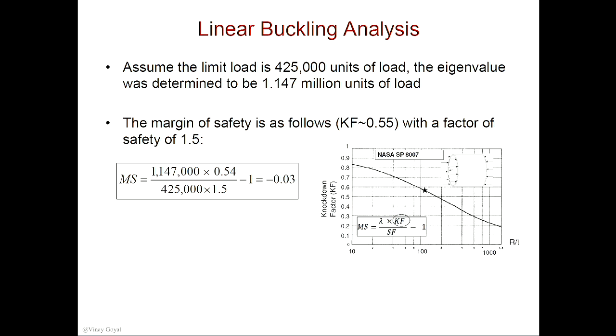And what I want to show you is how to approach the problem in a different way. Okay? What if I now model the imperfections? I put in the imperfections measured from maybe manufacturing, maybe through a laser scan, or I know imperfections that exist in my structure. And so I include that into my cylinder model. And now I run a nonlinear analysis. And this nonlinear analysis will tell me when the structure buckles.